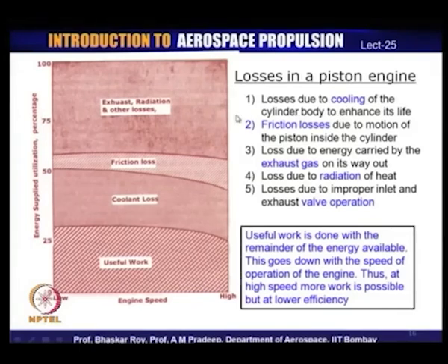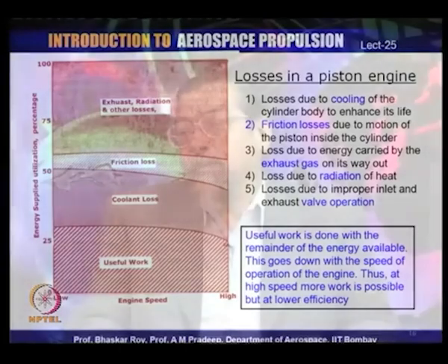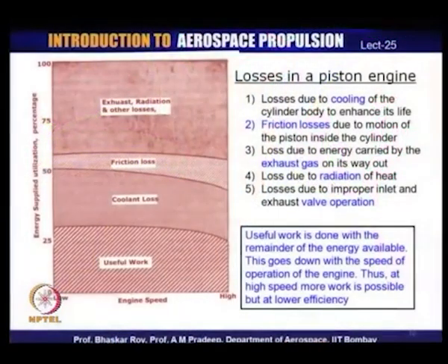Now, you see the cylinder is getting heated, we are burning fuel, the cylinder is getting heated, the piston is getting heated, and they get heated to very high temperature. In spite of the advancement of material science and metallurgy, the heat bearing capacity of these metal bodies has certain limitations, and if you have to provide them with a certain lifespan, which is often in terms of thousands of operational hours, then it is necessary that these bodies are cooled on a continuous basis to lend them a certain respectable amount of life.